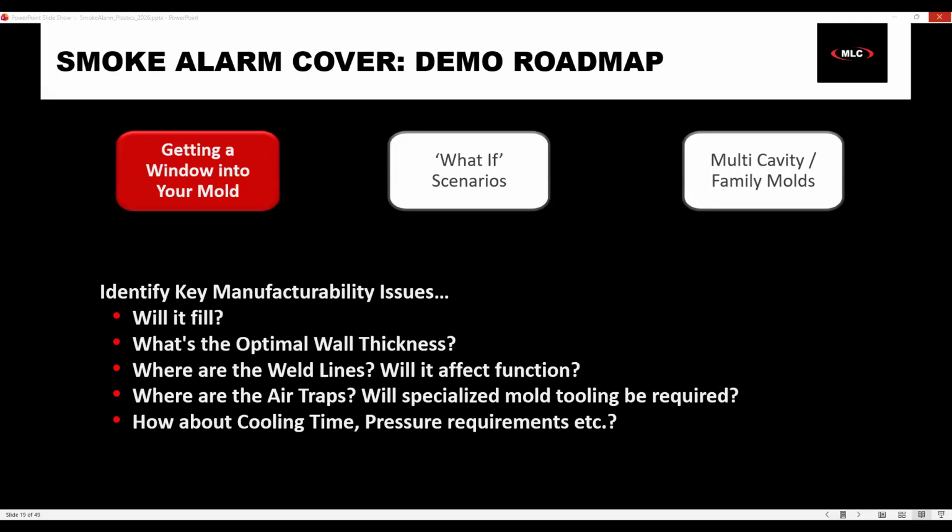We can see the pressure at the end of the fill. We can see where that is occurring. And so we're looking at maximum pressure, which is about 36 megapascals. So that's way below that 100. So that's not necessarily a bad thing. We can see the average temperature at the end of the fill. If we take a look at the yellow, we're around 300 degrees Celsius. Things cooking.